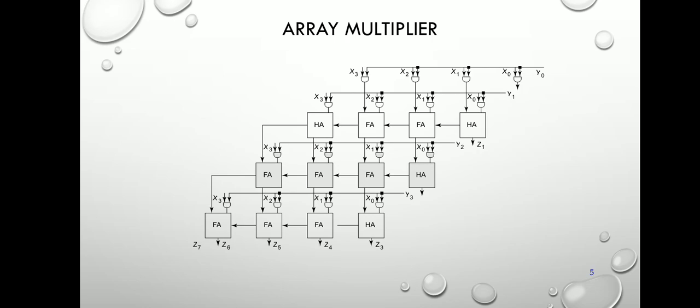And the next one is the array multiplier. This array multiplier is a digital combinational circuit which is used for multiplying two binary numbers by employing an array of full adders and half adders. It is also generally used in the simultaneous addition of the various products. By checking the bits of the multiplier one at a time, it requires a sequence of add and shift micro operations, which can be done with one micro operation by means of combinational circuits and produces the product bits at all times. This is the way we can multiply the two numbers, since all this takes is the time for the signals to propagate through the gates that form the multiplication array.